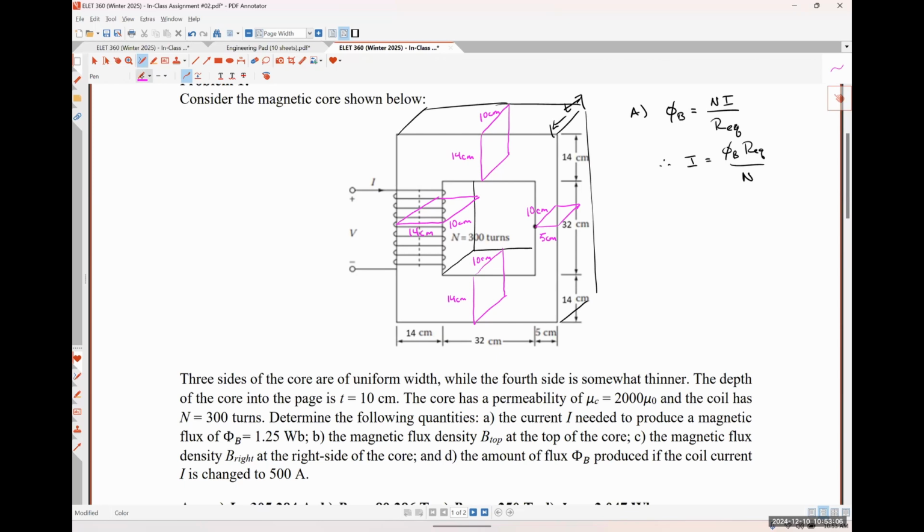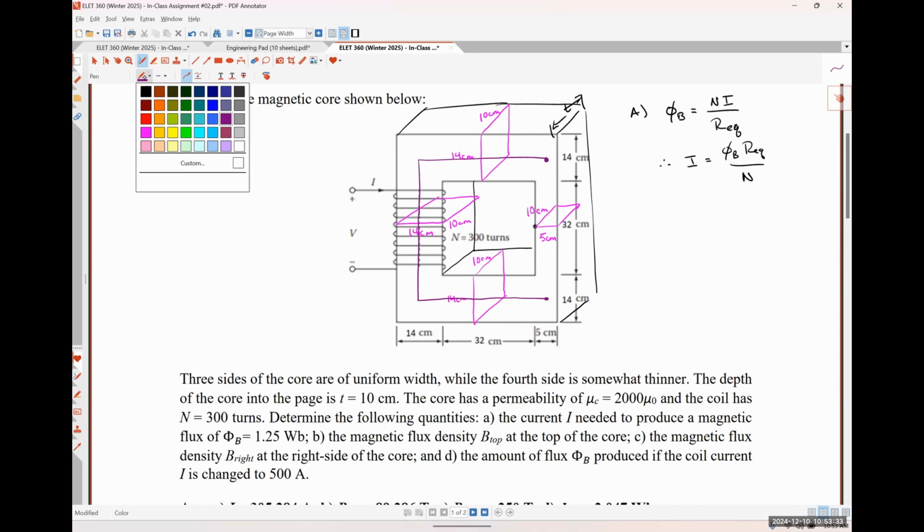Okay. So I'm going to do the flux path 1 in this color, right? So I'm just going to have a kind of guesstimate here. So let's say that it starts right here, goes all the way across like so, down like so, all the way across like so. And this total length, we're going to call L1. And then I'll do the other flux path length in a slightly different color. Hopefully this looks different enough on the screen. Can you tell the difference between that light purple and the darker purple, or should I use something else? I can tell. Okay. And let's call that guy L2.